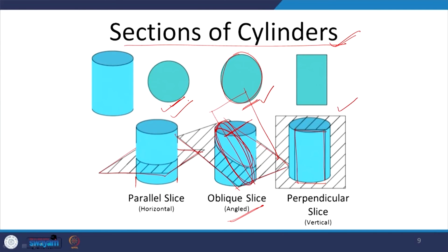If you have these concepts in your mind formed, then it will be very easy for you to draw sections, and you will very rarely be going wrong. And side by side, you will also have to keep the fundamentals of orthographic projections in place, that all the time vertical and horizontal projections should meet and result in the final point of the projection.